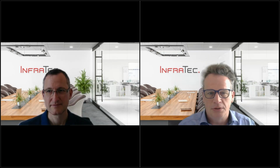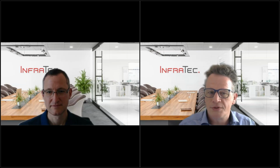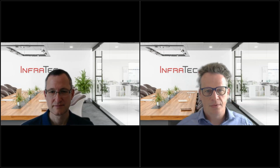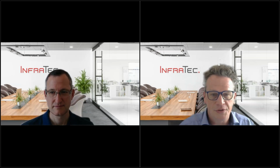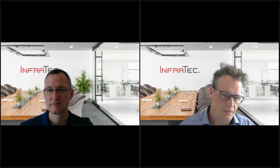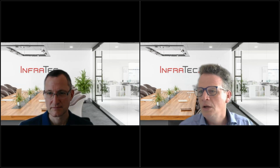It needs to be a special mirror, because the properties of glass for the reflection of infrared radiation are not as good as, for example, those of metal surfaces or other materials. So it's a special type of material. Glass in this wavelength has the property to absorb a lot of the radiation, and that would not help you much for the measuring task. Okay, then